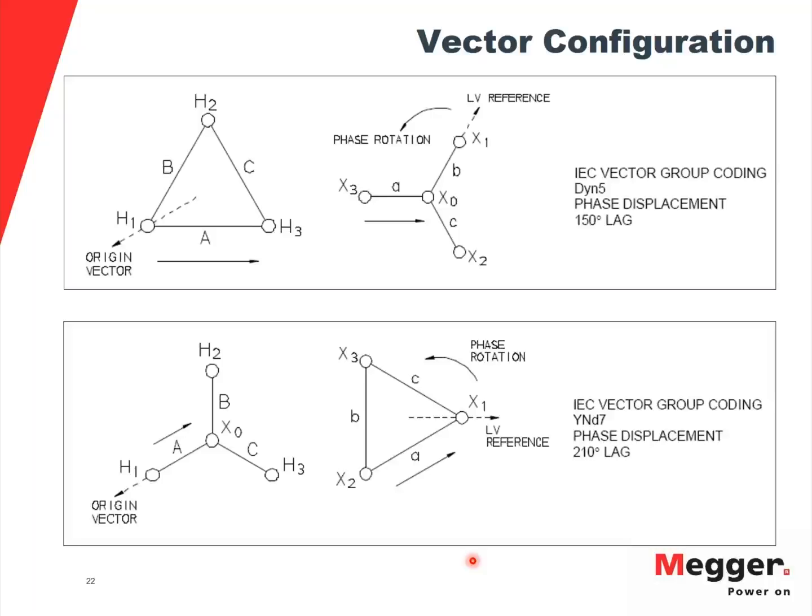Okay, let's look from the physical point of view. The first thing you have to remember is that a transformer is mainly a big inductor with a very, very small resistance. And when you apply DC for any process of saturation or demagnetization, you are playing with the time constant, which is the relation between the inductive component and the resistive component of your transformer. So you cannot split those two apart. And that means that there is a time function for you to see stability on your variation of current with respect to the variation of voltage.